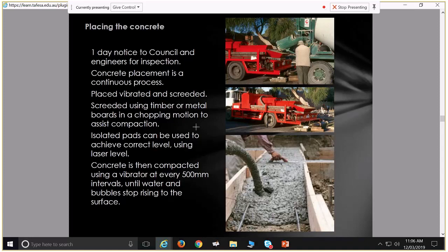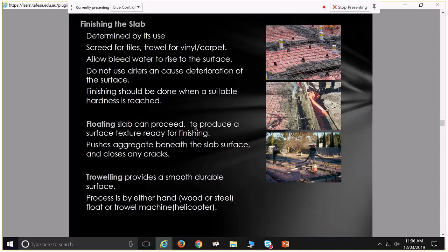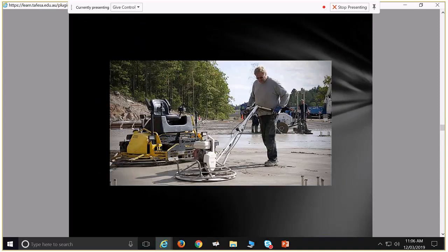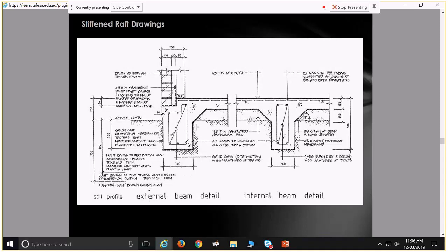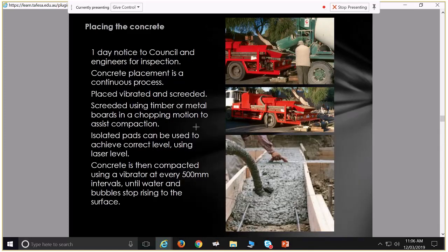And as you know, something is only ever as strong as its weakest link or its weakest section. So concrete has to be thoroughly vibrated down into the formwork. There's several ways of doing that. But your typical concrete vibrators, there's a two-stroke engine that's going on someone's back, and they've got this large flexible piece coming off that and a rod that just shakes around like crazy, and they plunge that rod in with the concrete when it's all placed to settle it all down and to move it all down and get all those air bubbles out. That's one way of doing it.